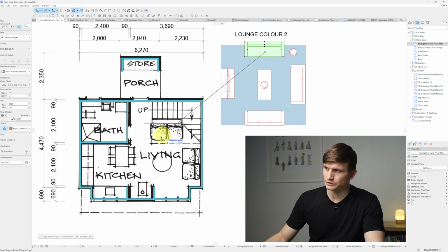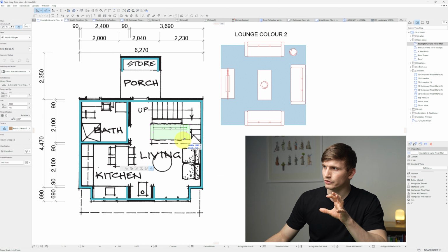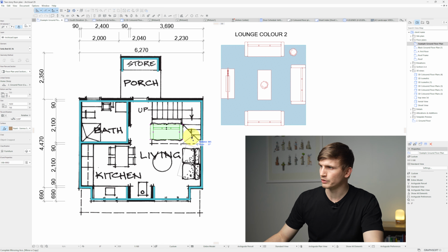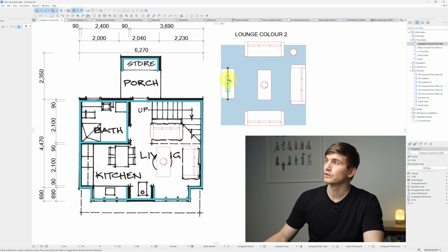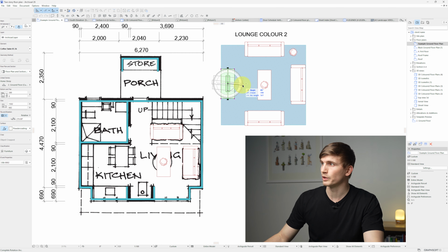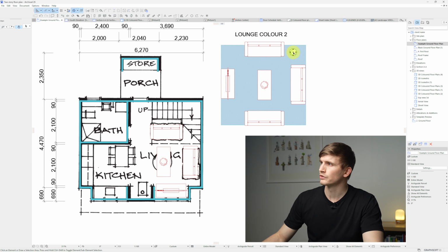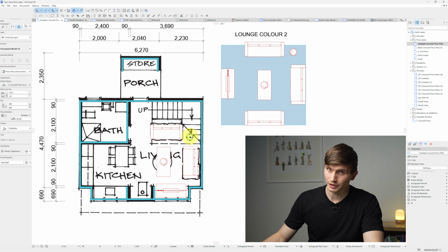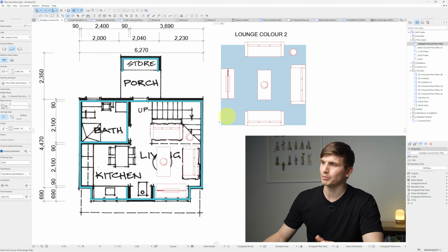We can now drag our lounge into place and reconfigure the size so that it suits. Let's mirror that across just to here. We'll take our central table just here, bring that one in, as well as our TV. We'll rotate that one around and drag that down into this little empty space just here. Let's not forget about the pop lamp. We'll pop that one just in through here as well. Let's use the eyedropper to pick up the carpet and then place it just underneath the lounges as well.